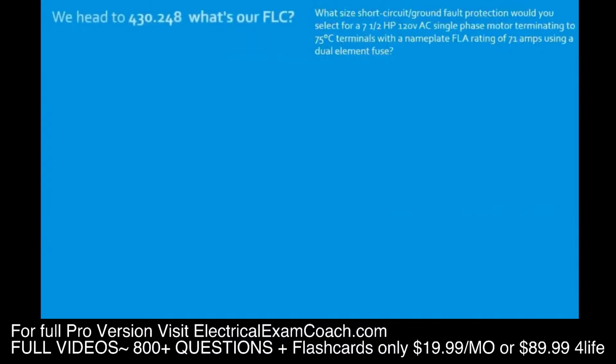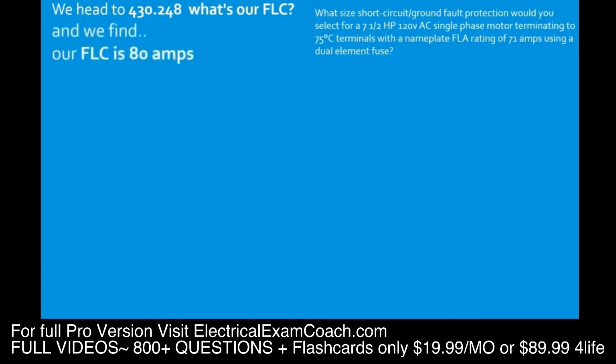Now we head to table 430.248. What is our FLC? We start on the left-hand side, find our horsepower, come across to our voltage, and we're going to find that our FLC is 80 amps.